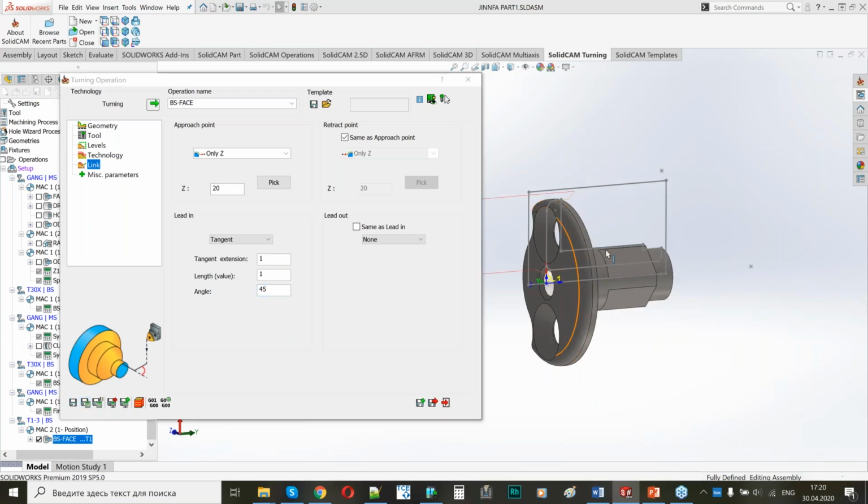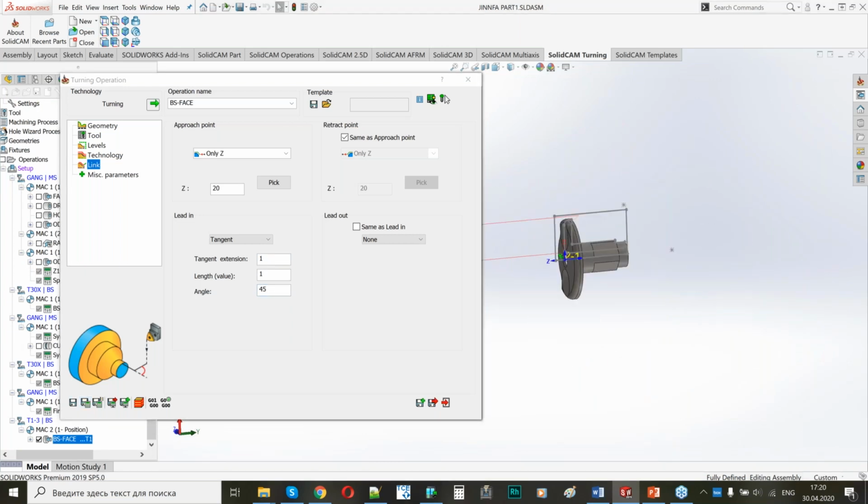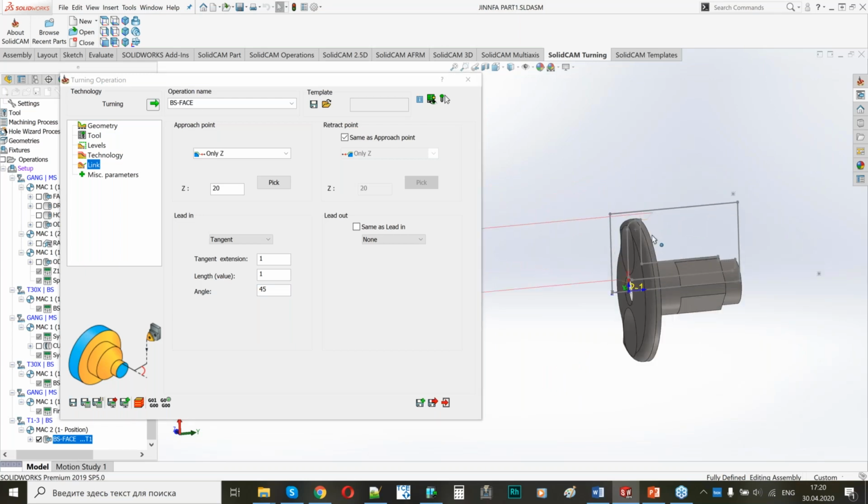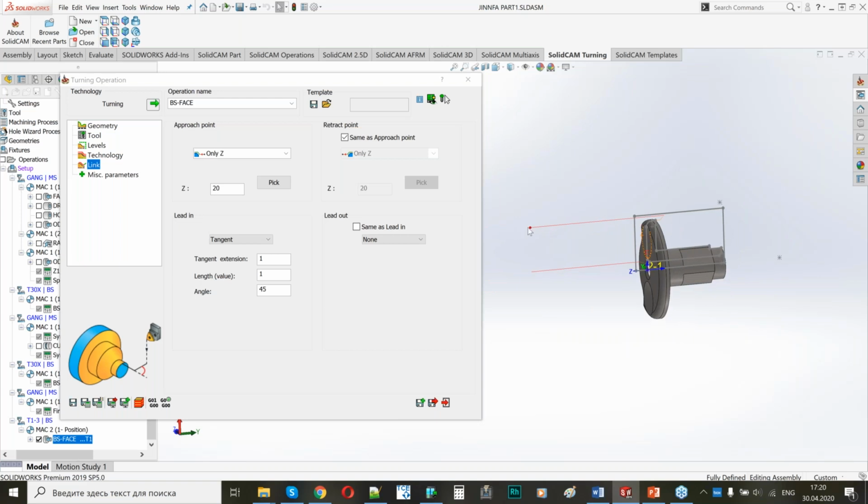So this is my toolpath for the facing. It looks strange for the mill-turn machine, but for Swiss type machine it will be very good, because the part will move safely and it will retract before going to the next tools on a tool table.